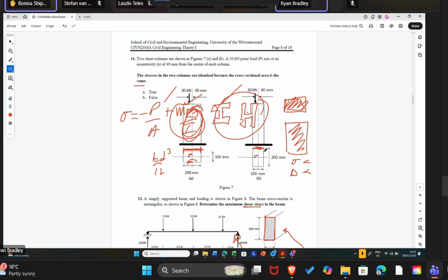So we can see here that in this arrangement, here is the axis about which the bending is occurring. That's the depth. Here's the axis at which bending is occurring. This is now the depth. So because this is now the depth, this becomes far more critical. All right. If this load is offset here, the bending becomes a lot more critical. So we can think of it like this is a shallow beam, and this is a deep beam.